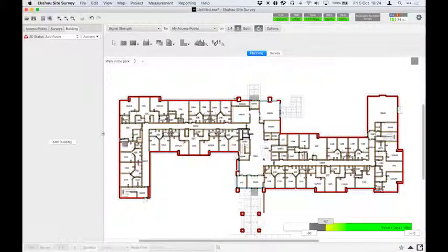I know that this site is actually 82 meters wide to be precise. So I'm going to click and drag across while I'm holding down left click. You see the CAD import has actually brought it up as 78 meters there. So I'm going to release my left mouse button and just type 82 and hit enter to set that scale. So the scale is set for that plan properly now. Each time we use a different element of these tools at the top, to return to the view or the manipulate or edit option, we just click the mouse pointer, and then that's what we can do by selecting different elements. So we've got the scale there, which is great.